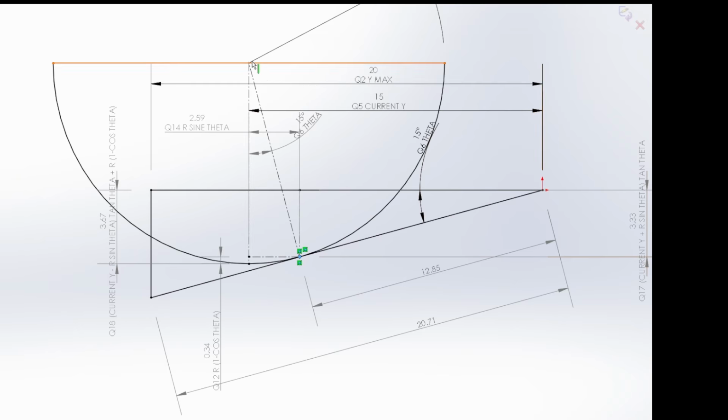And instead of the actual cutter Y position being along this line here, this distance here, the current Y, in fact it's going to be cutting at this point here. So I have to take away or calculate using this compensation here to get from this point to here for the cutter to be in the right position to cut along the line.